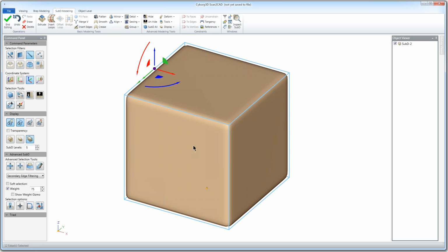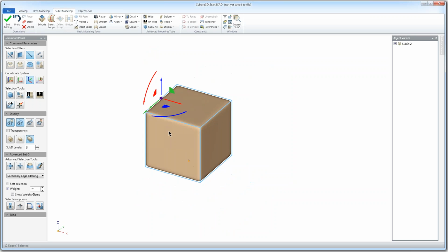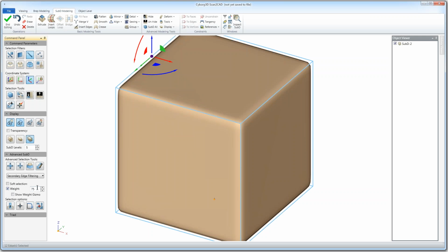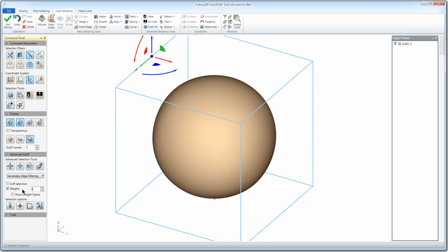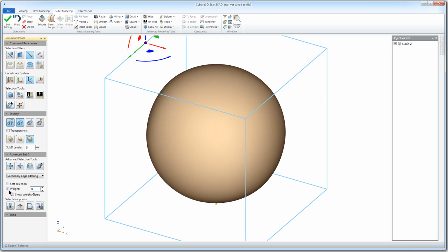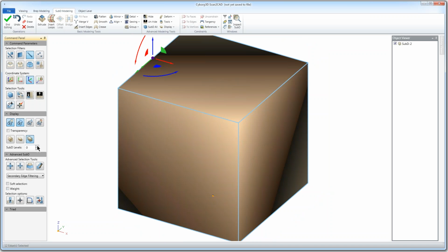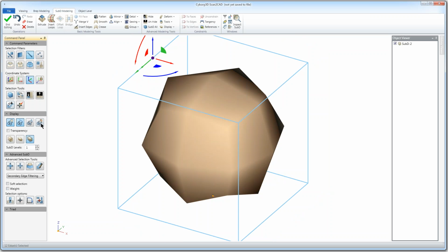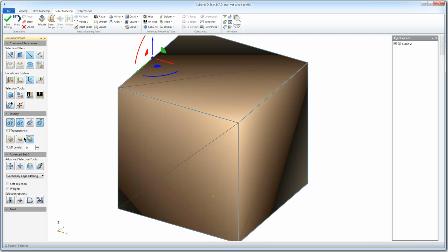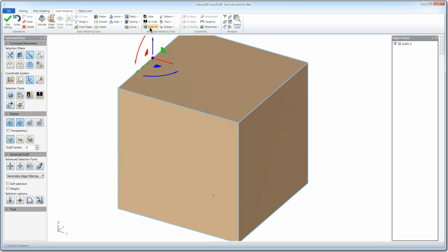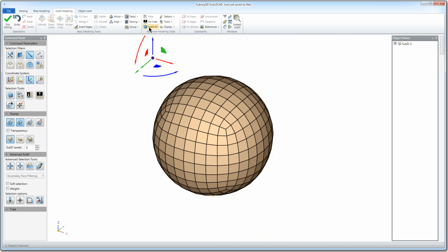So let's talk about how the SubD actually works for a second. What's happening in the subdivision world is that each face gets subdivided per subdivision level. So if we take this model and go to 0 subdivisions, you can see it goes right back to the original shape. If we use 1 subdivision, each time we do a subdivision, we get 4 times as many faces as we would previously. So, for example, the subdivide all operation shows you what would happen if you do more and more subdivisions.